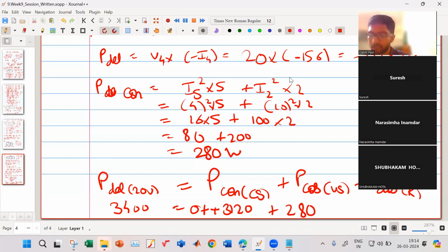Okay. My question is, I2C is like a protocol. So based on that protocol, you have written a block which will do the communication, sending and receiving, right? Yes. Externally, we'll be having the device. We'll write from that particular module to the device, and then we'll read back the same from the device. Internally we have another interface which will be reading the data from the device, what we have written. So this module will do both, bi-directional.